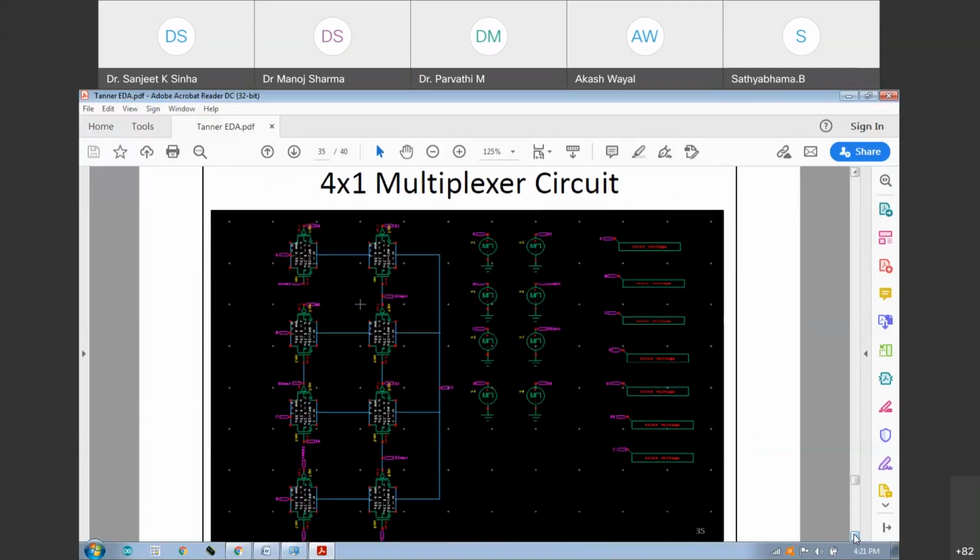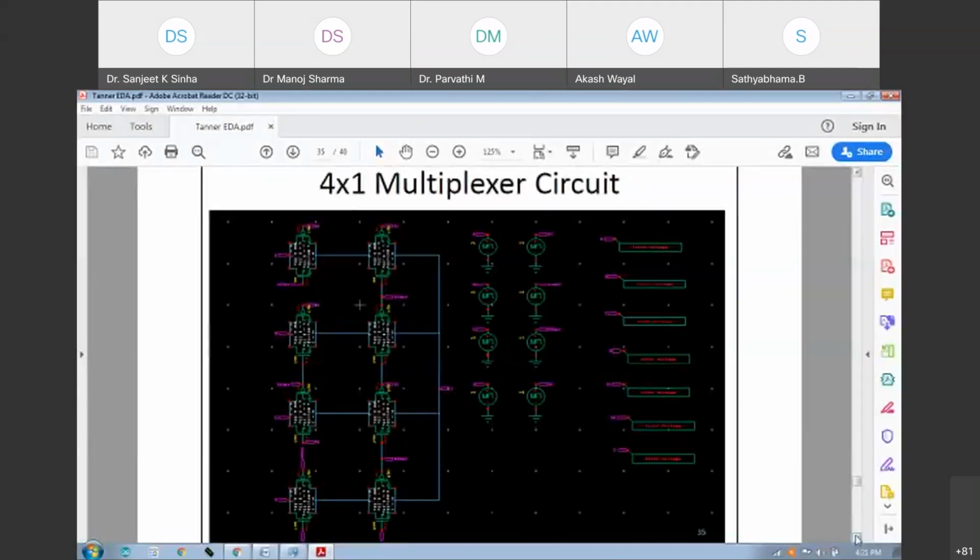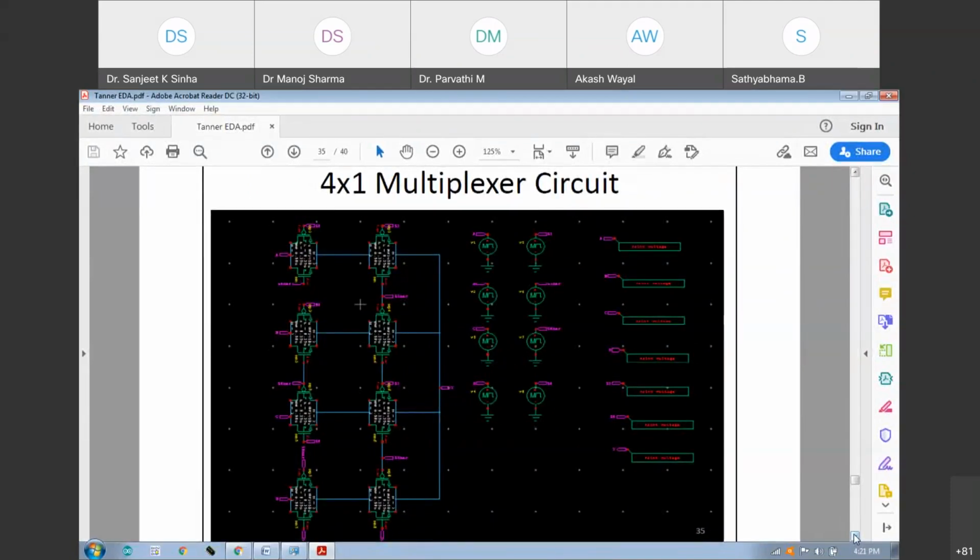Yes. So this is the typical implementation of this particular 4:1 multiplexer. What will happen in a 4:1 multiplexer? We have 4 inputs and 2 select lines. These two select lines have 4 options: 0 0, 0 1, 1 0, 1 1. So we need two inverter-type operations on the select lines. That's why in that design 2 NOT gates are there.